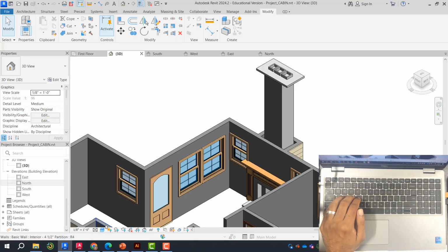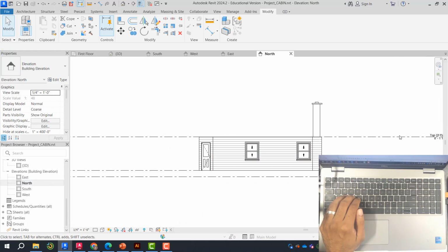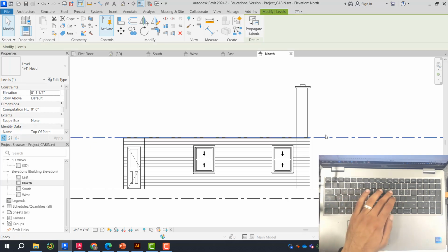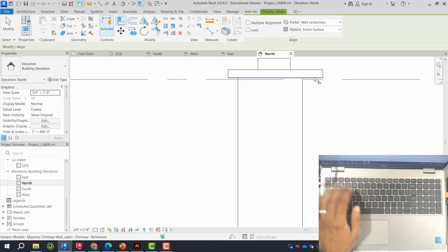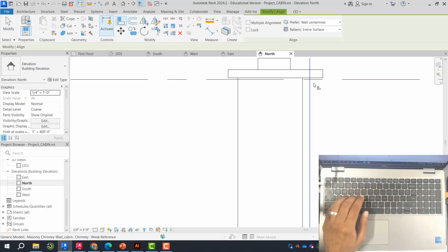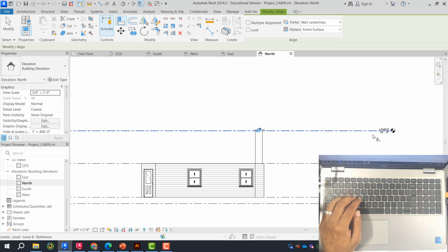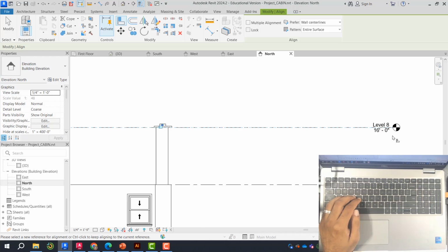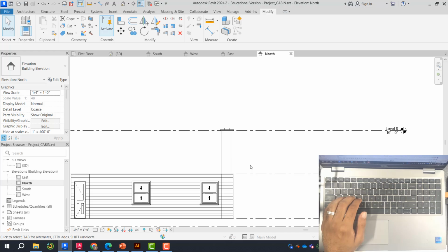So going back to the Revit model, I'm going to go ahead and pick one of the elevations. You will be able to see the chimney here. I'm going to copy this to the top. Here, I can use the Align tool to make sure it's lining up. AL, select here, select there, and I am completely lined up at 16 feet. So 22 is a far stretch. Let's go ahead and modify the chimney.